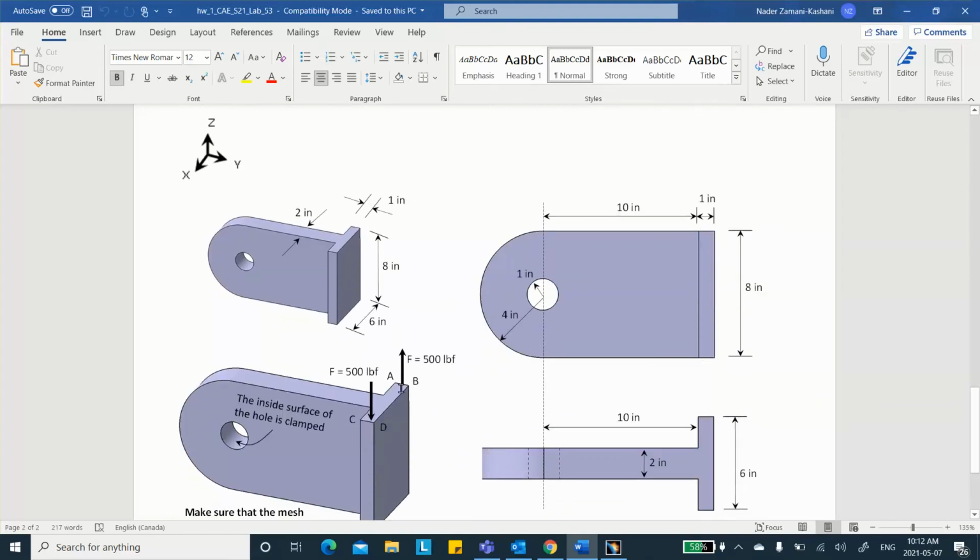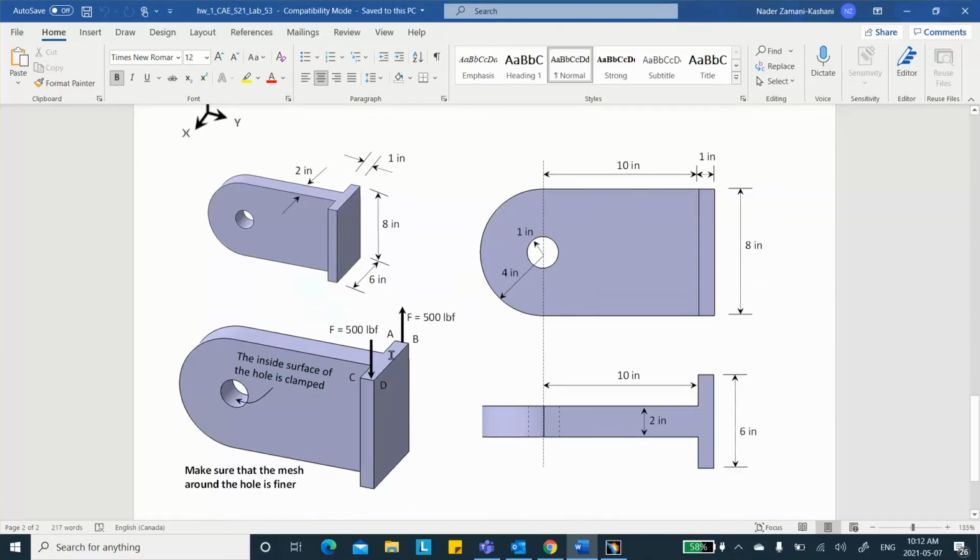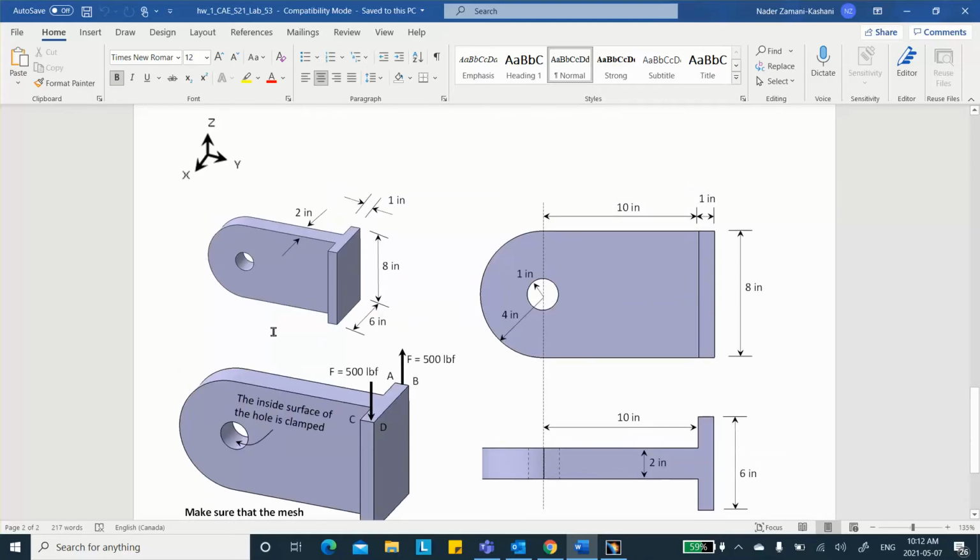Now, problem number two is exactly the same geometry. The only difference is that the force is applied on these two edges. On AB it is up, and on CD it's down. Now again, you look at the common sense. If you apply a load like that, this thing will actually twist. If it's twisting, then there is no plane of symmetry. In the other case, we were pushing this thing along the y direction, same force, same location. So it made sense in problem one to set that YZ and XY are planes of symmetry, but not here. Okay.